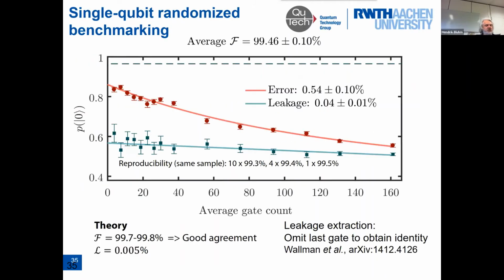What I can show you is, first of all, that it works. So we achieved a high gate fidelity of 99.5%. I think this is still the record for the system, which is significantly affected by nuclear spins and also in practice charge noise due to this exchange-driven drive. We also find a good agreement within a factor of 2 or so between our best effort model and the experimental results. So that's nice from the device and qubit perspective.